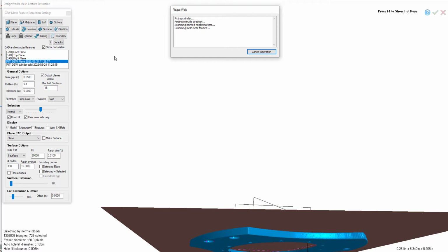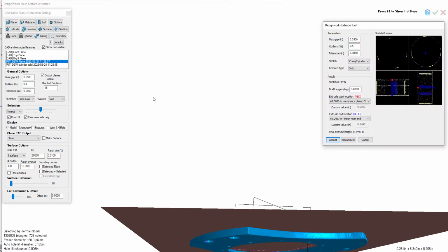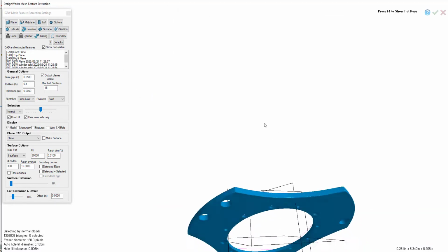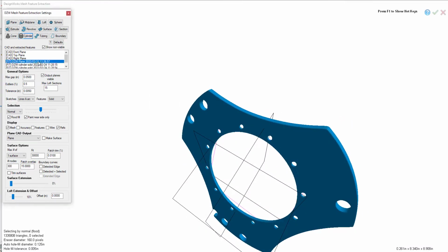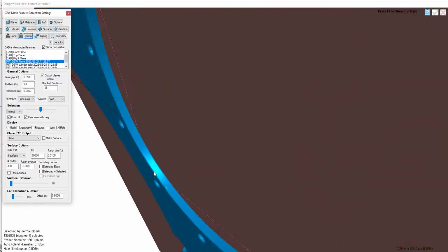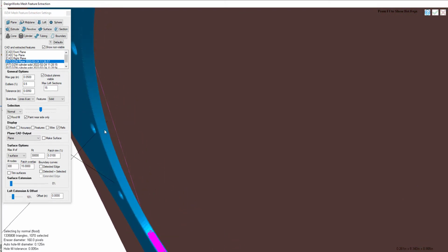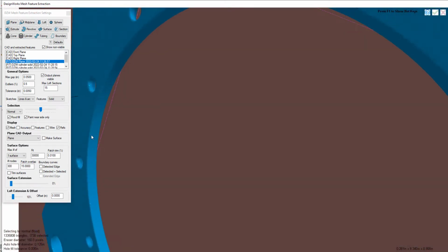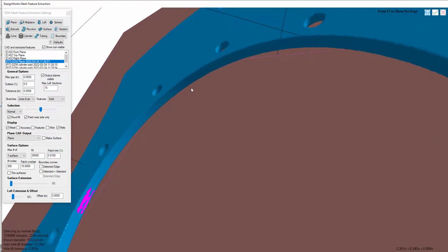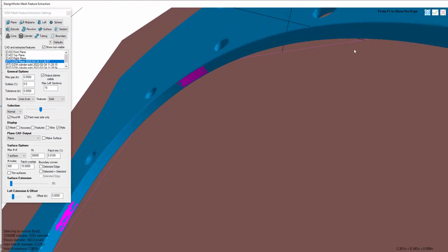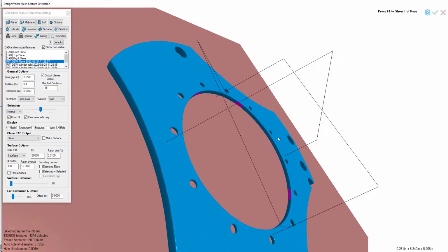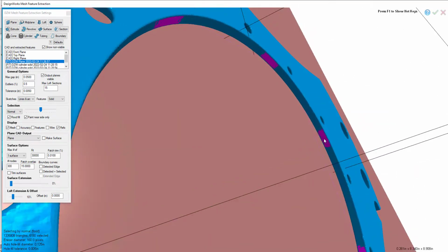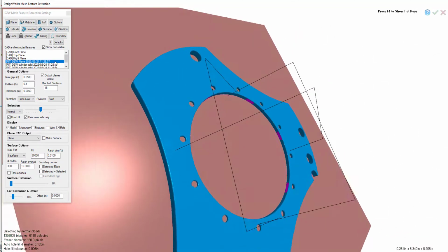And then we'll do this one more time for what we need to find the big circle there. So again, we'll come in here, define our constraint, left mouse clicking on here. It's defining it. You wouldn't want to define it by just a few little points. You wouldn't get a best fit. And we're on the constraint. Again, we'll just repeat. We want to do a cylinder.